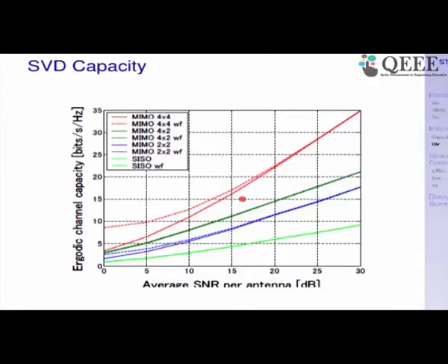Okay. So the last slide that I have shown you, see the last slide here. This slide basically answers the question. We have shown that for high SNRs, equal division of power among all the modes is going to be the same. So the capacity with water filling and without water filling is merging at high SNR. But at low SNR there is going to be a difference. I hope that answers your question, KSRCT, right? The second slide I have shown: at high SNRs there is no gain, at low SNRs there is going to be a gain.